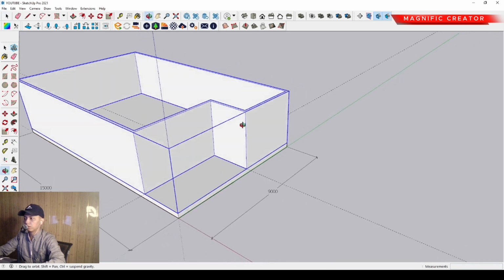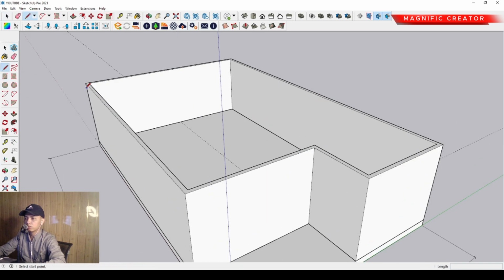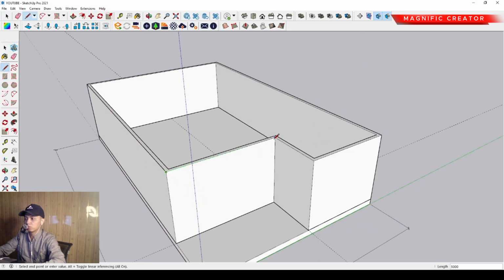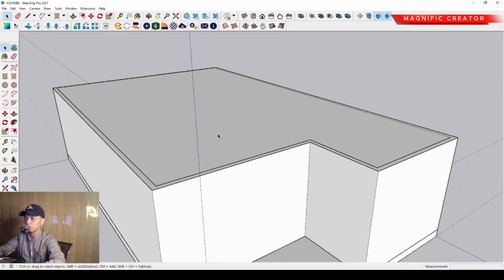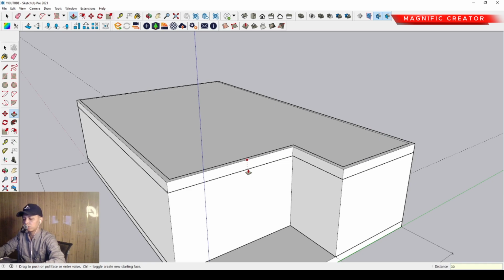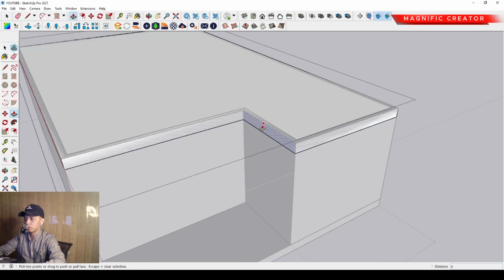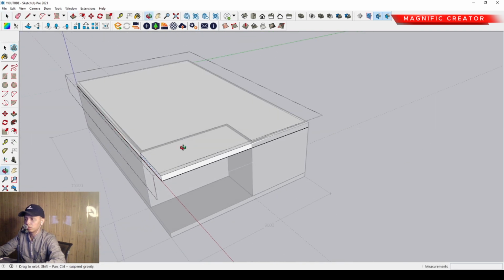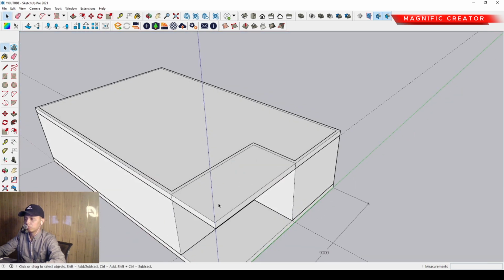And we can also make the other floor. We can use the second floor, starting from the corner and going through all the corners in here. You can draw it until the plane shape appears. Then we can push it down around 300 millimeter, and then make it a group, and maybe we can complete the first floor to be a full area of the floor in here. Okay, the full area.